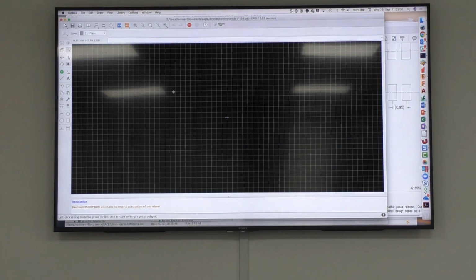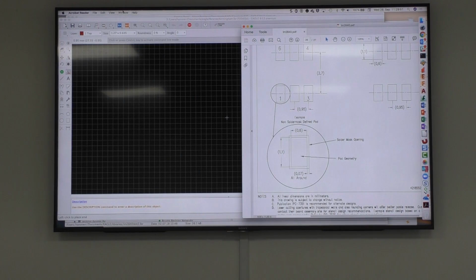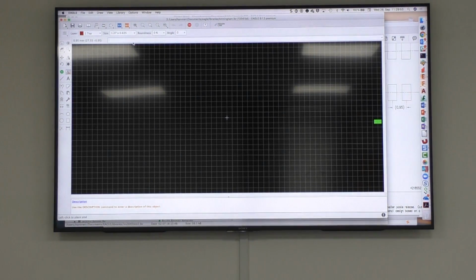So, I need the SMD command, that's this one. Here you are. It's in top layer. The predefined sizes, you can be 99.999% sure that you will use this value that's there. So I simply say, what was it? 0.6, 1.1. So I type simply 0.6 space 1.1. Enter. Here it is. That's the correct size now.